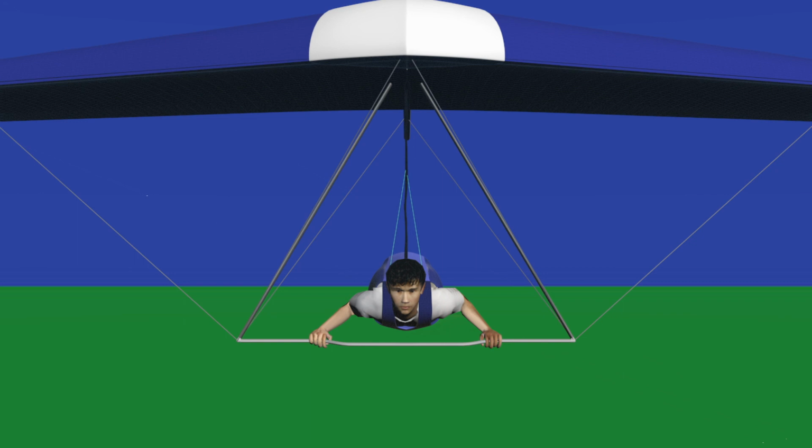How can all of this be translated to a virtual experience? We want to give the pilot in the flight simulator, as much as we can, the feelings he has in a real flight. But we cannot virtualize the centrifugal force, nor can we virtualize the resultant. What we can do, though, is manipulate the horizon, since it's a virtual horizon. When the pilot has his VR glasses on, he has no visual input from the outside world, only the visual input from the VR headset. And we can use this and gravitational pull to trick him into thinking he is in a turn and he is feeling the resultant force.